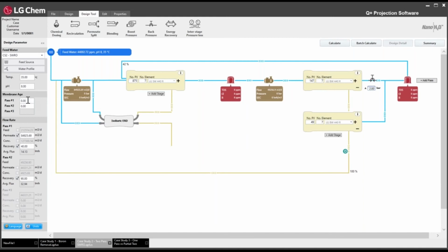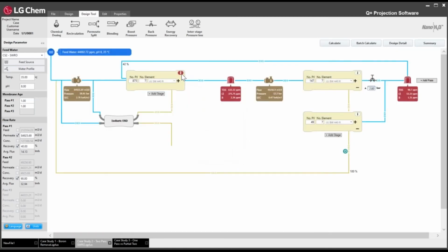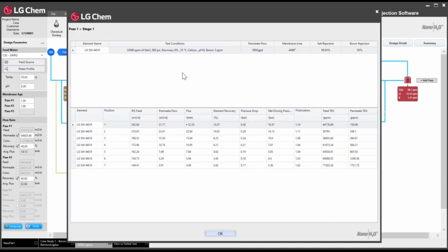If you're not going to be cleaning within the first year, let's just say the first cleaning will be at the end of the first year. So that's the first time the N-1 operation condition will occur. So when we change this to membrane H1, and we hit calculate, now you can check on the flow balance. You'll see 32.3 is the target, and we're at 32.33, right? So we're basically right at that limit that we were trying to target.